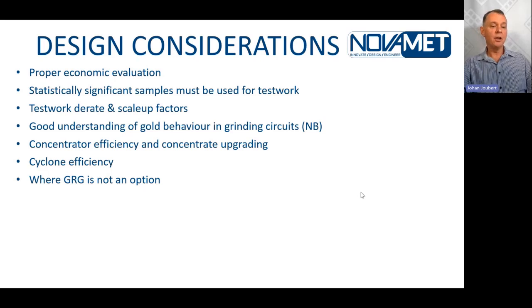Then as a designer, you might be faced with a point where you have to say, no, this is not the answer for this project, and walk away from it. If gravity gold does not add value, do not install it for just the sake of installing it. There's other technologies that are much better suited. For example, if you have a lot of fine gold, then rather install a flash flotation circuit. So do not just install for the sake of installation.